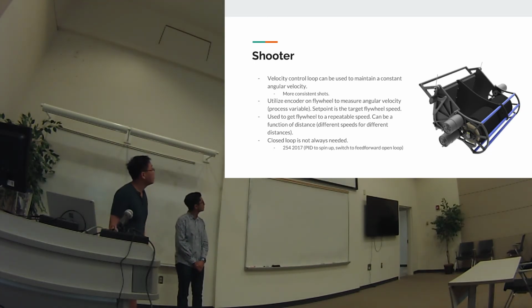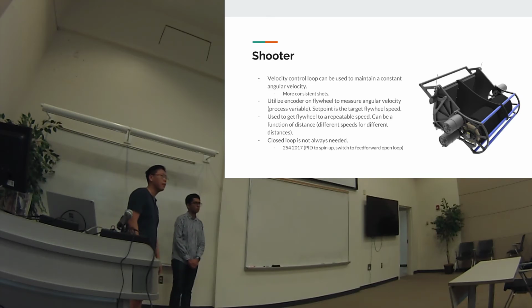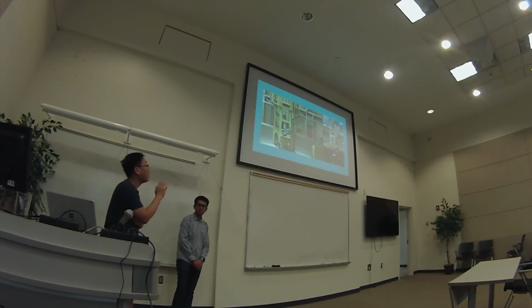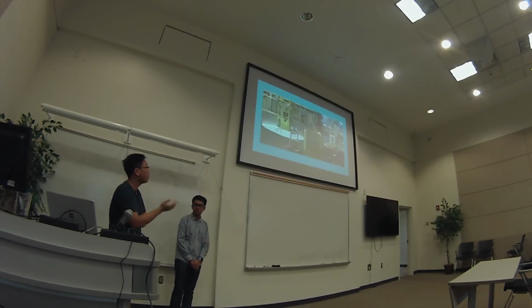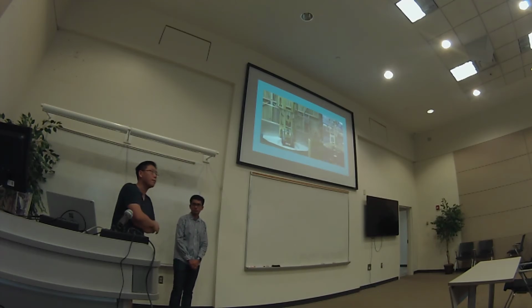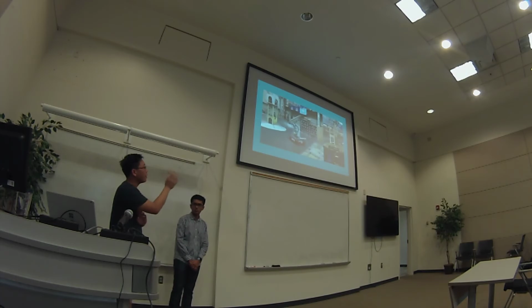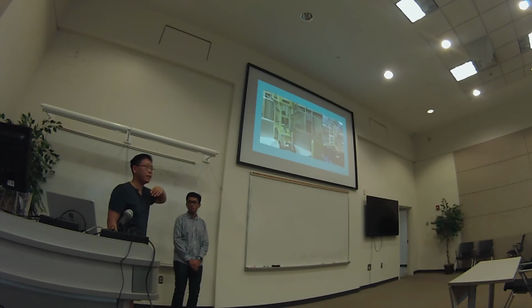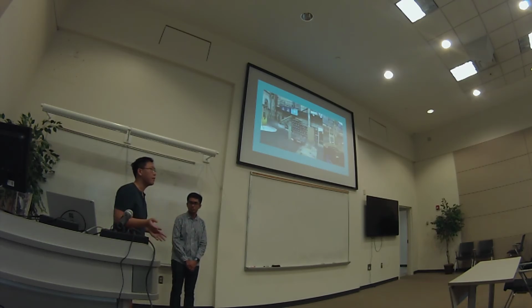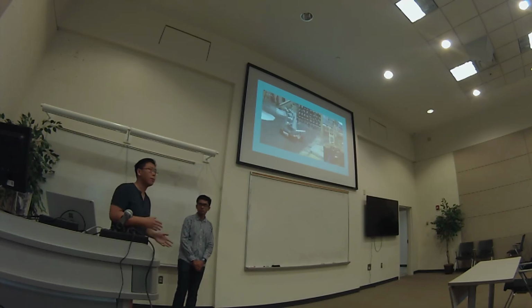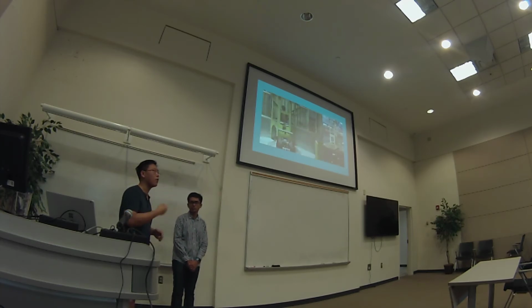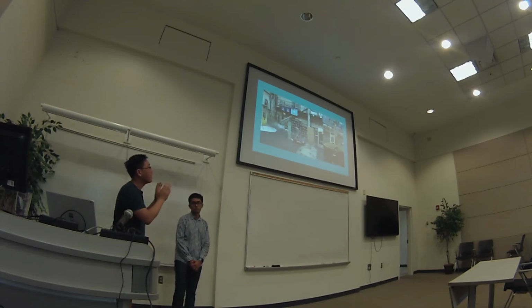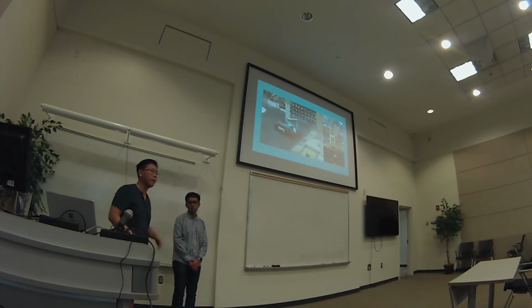So now, looking back at the initial examples we looked at, we can understand how each system is working. With the one on the right, it's all the vision stuff Mannit was talking about. They have their green light reflecting off the retroreflective tape, then they're getting the angle difference and setting it on their control loop, probably with an encoder on their turret measuring its rotations. Then they can consistently aim at the right place despite the motion of their drivetrain.